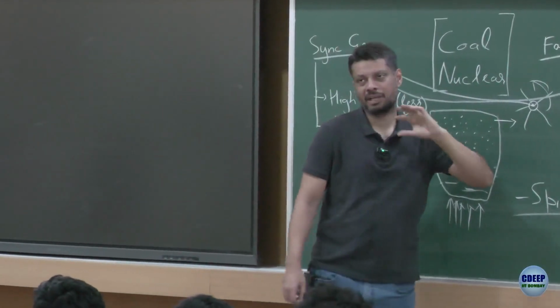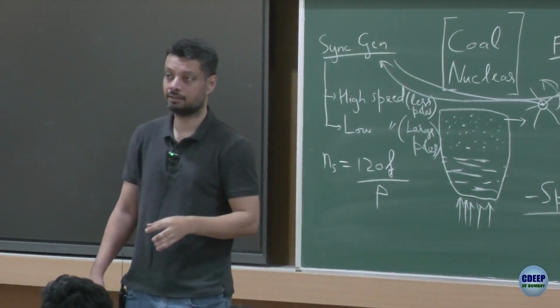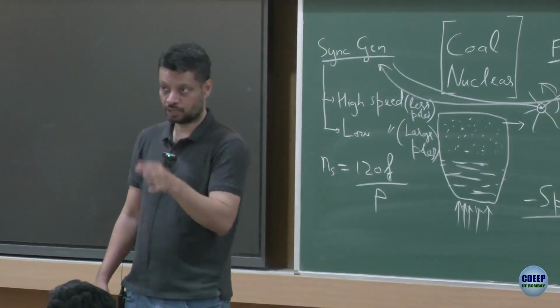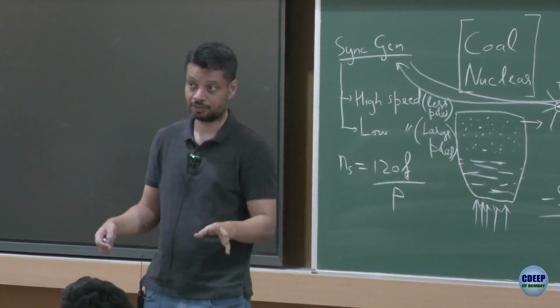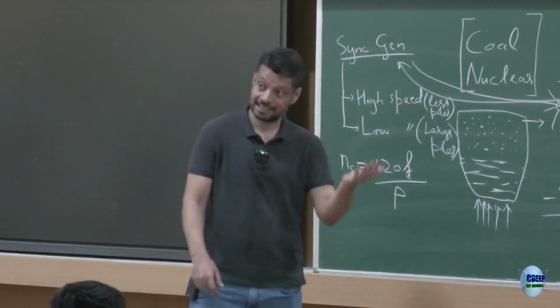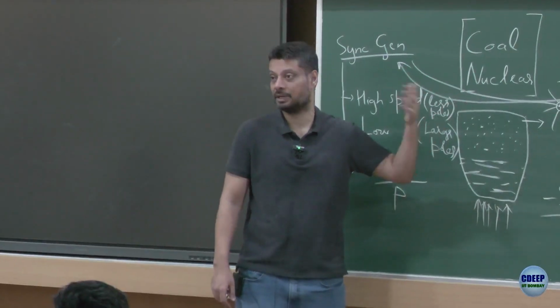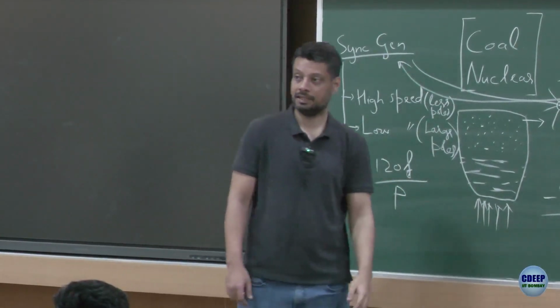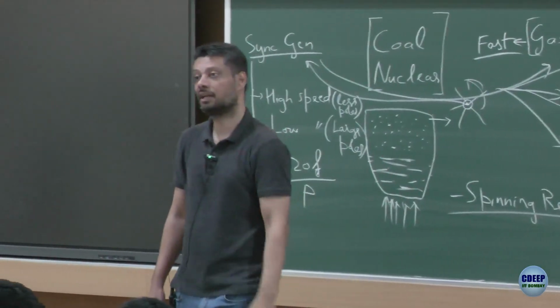You would directly burn gas and use it to run a turbine. Once the turbine is rotating, whatever comes out of the turbine is still relatively very hot. You can use that in a secondary cycle to build steam and then run a secondary turbine. You can do that, right? So you can have direct burning plus a steam cycle for gas.